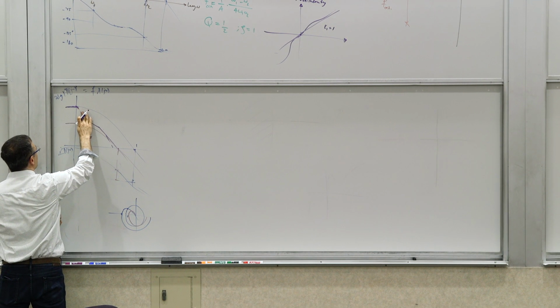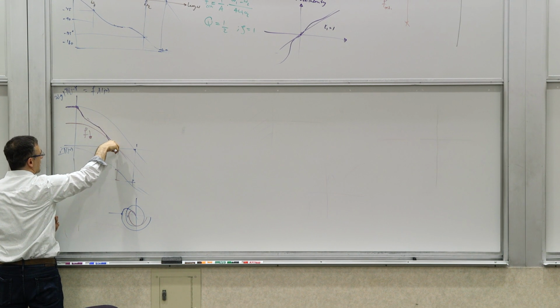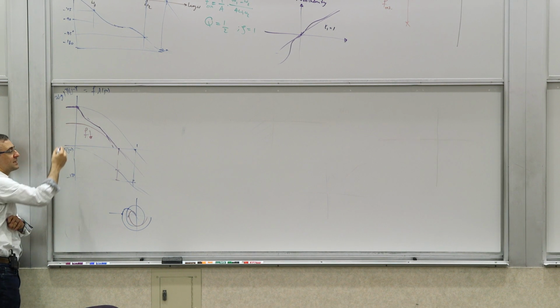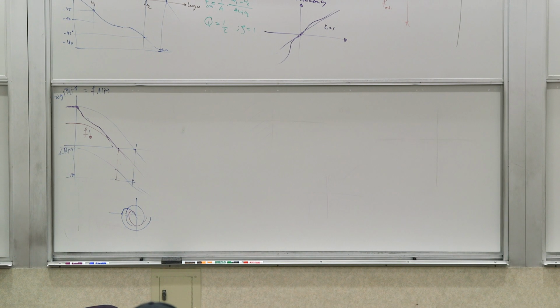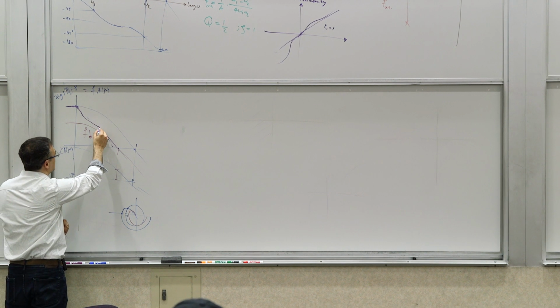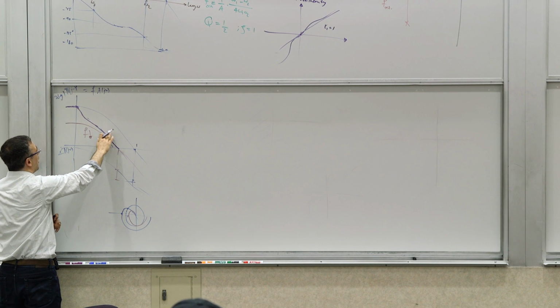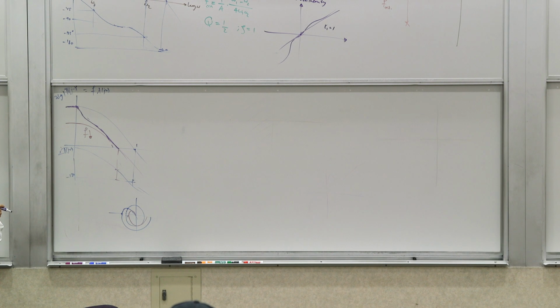What if I could reduce my gain here, so that at this point the gain is low, but at low frequencies, for example here, I still have large loop gain? So at least I will get the benefits of feedback at low frequencies, but I would not let this loop gain be too large at high frequencies. Basically, at low frequencies keep it high, but at high frequencies drop it. That would improve my performance, right? It can stabilize the system.